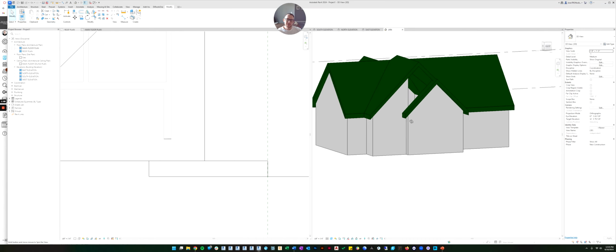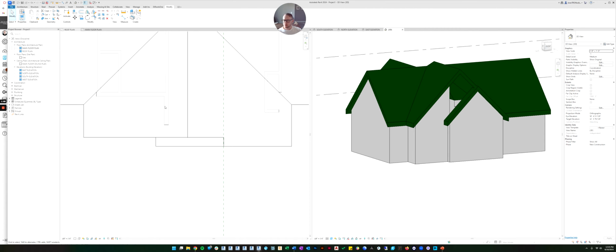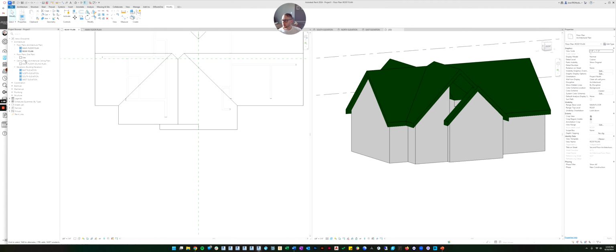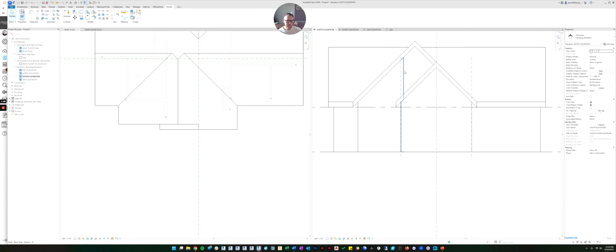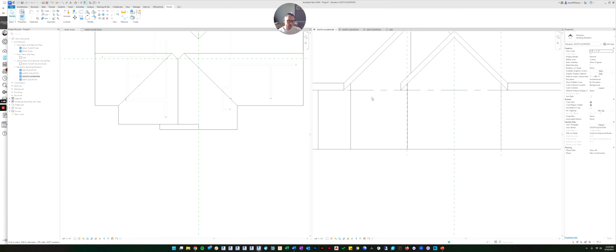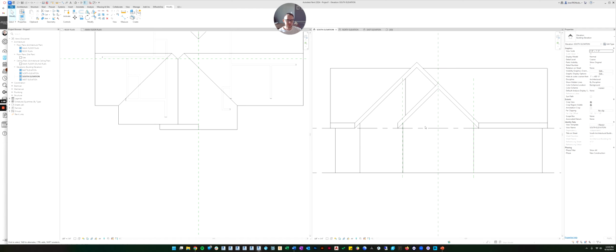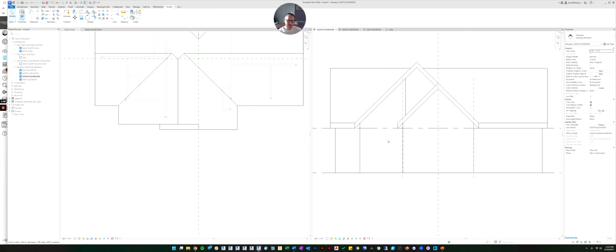And you're going to use a technique that you haven't learned yet, and that's you can edit the profile of a wall. So to see what I mean, let's go to the south elevation where we can see this wall. And we're going to try to select the wall. You need to grab the edge in order to get the wall, or something else that's new, that's a handy tip. Sometimes it's hard to select the edge of something.